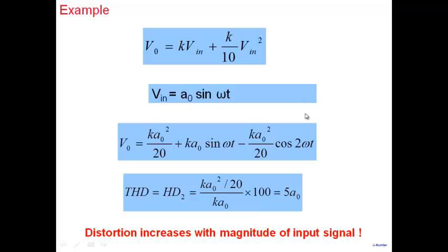And in general, all that it is illustrating also is that I have nonlinearity in my device. All my transistors are nonlinear, and therefore I will get distortion. And distortion then becomes very important. It also tells you that when you specify distortion, you always have to specify distortion at a particular level. Here it is being written as at a particular value of input level. I can also specify harmonic distortion at a particular value of output level here.